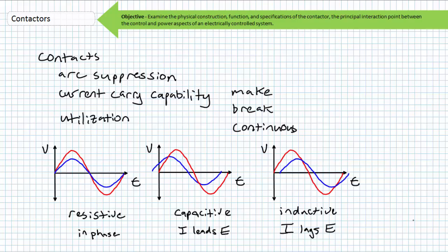High-power contactors use arc chutes to divide and cool the arc. Blowout coils or other magnetic means deflect the arc into the arc chute. Vacuum contactors have nothing inside them to ionize in the first place, and the arc is extinguished upon opening. All these methods share the same goal. They terminate arc current very quickly. The contacts of a contactor have three typical current ratings dependent upon application: make, break, and continuous current carrying capacity.